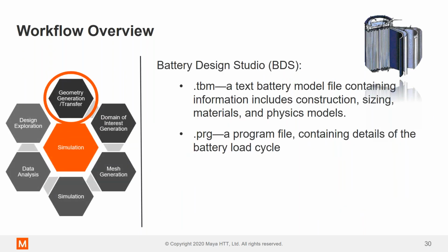So now we're going to jump into the first step, and that is covering the geometry transfer within Battery Design Studio. So just a quick overview. The first thing that's important to generating a battery cell within Star CCM Plus is a file known as the TBM file from BDS. It's a text file which contains all the information, including construction, sizing, materials, as well as the physics model. And we're also going to import a PRG file or program file which contains all the details of the battery load cycle.